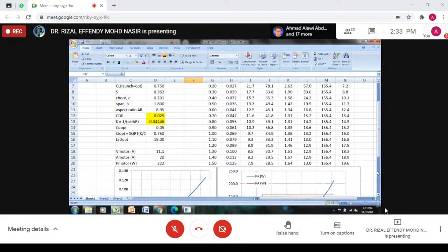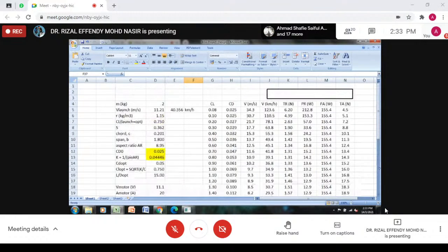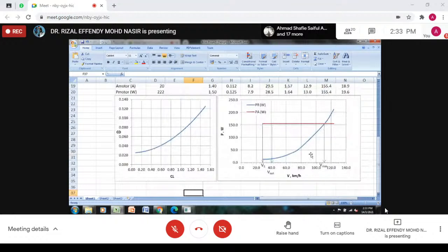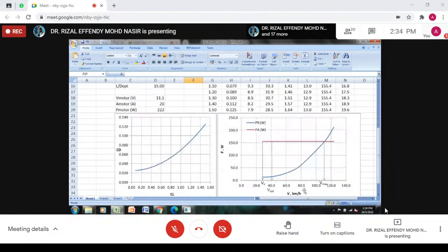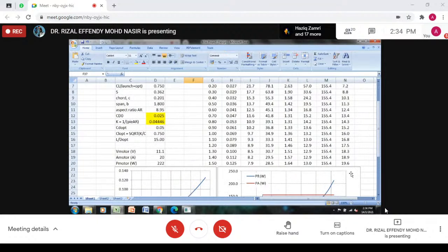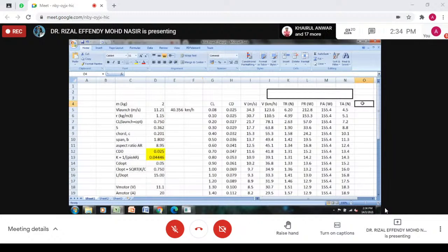Okay. Now, once you get the power required versus power available, you dah tap all the Vmax, Vstall. Vstall is a Vmin lah because you ada excess power banyak kan. And then you ada optimum speed. Okay. You design for maximum CL over CD. So, it's supposed to be the speed lah. Bukan minimum power tapi minimum drag. Okay, now you nak calculate ialah rate of climb.